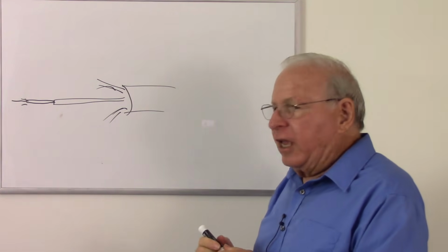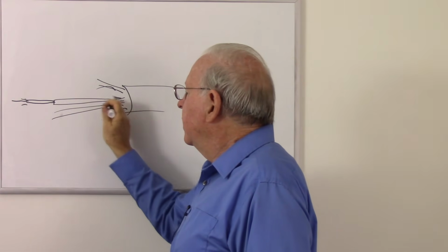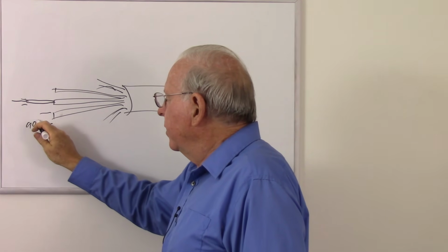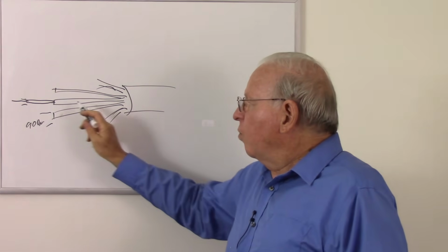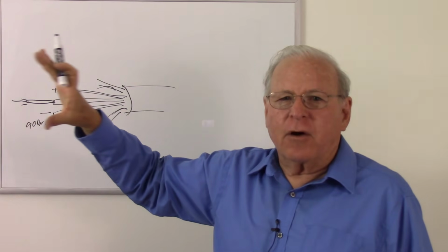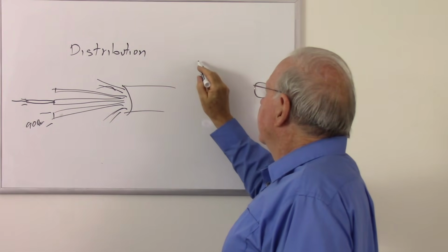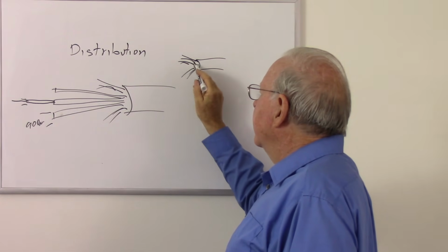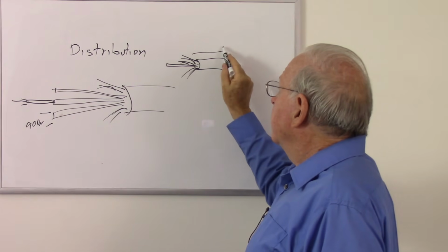Another type of cable you might see is going to once again have that tight buffered fiber, but instead of just having one, there's a ton of them. So I'm drawing these kind of big. Remember, these are 900 microns, about a millimeter in diameter, so you have a whole bunch of these all packed together. And so if you have one fiber in there, it's called simplex cable, but if you have a whole bunch of them, it's called either tight pack or distribution cable. But if we go back to our simplex cable, so there's our Kevlar coming out of our jacket, and a single fiber, which is about a millimeter. If we take a whole bunch of those in a bundle,